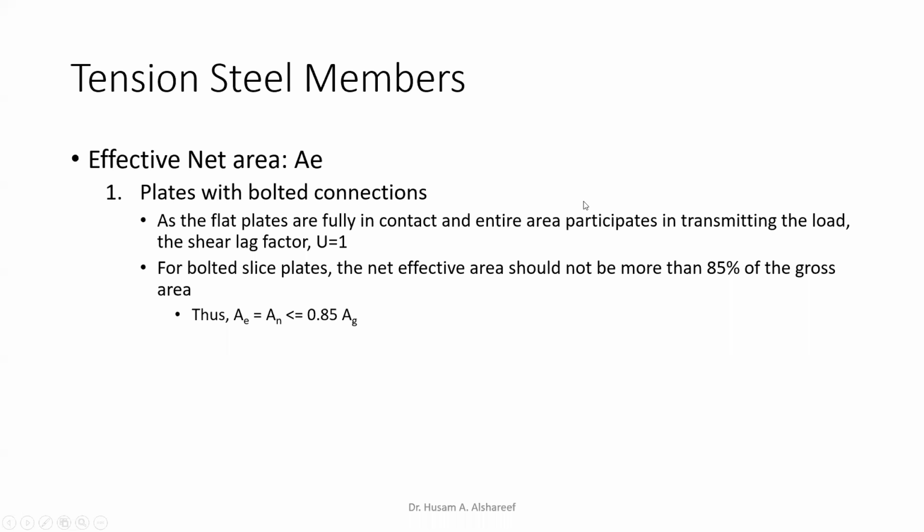Well, hello everyone. This is part 3 of the tension steel numbers. And since we solved a problem in part 2 about the net area, today we're going to continue on the effective area. So I'm going to share with you 4 scenarios of how to find the effective area, more so of finding the shear lag factor, the U here, this value, the U.